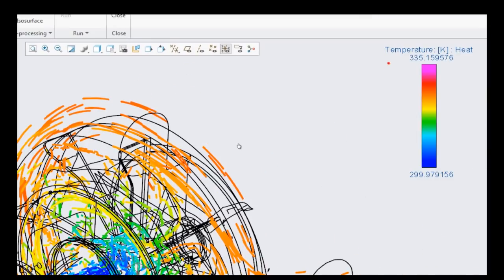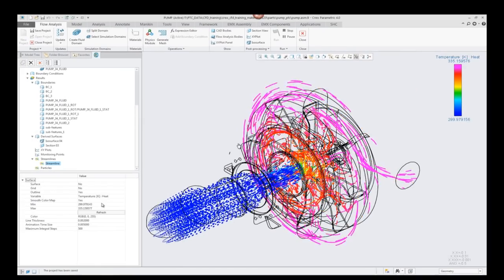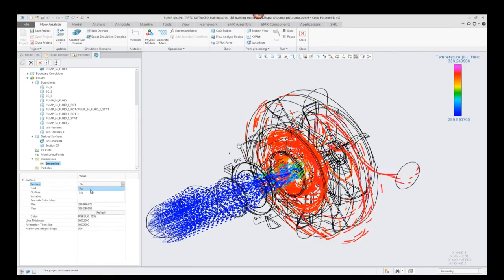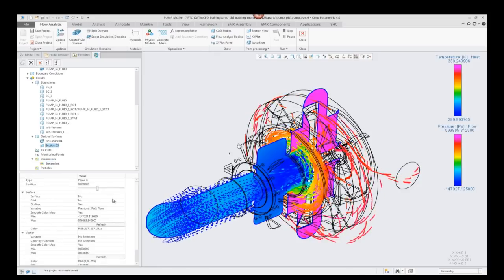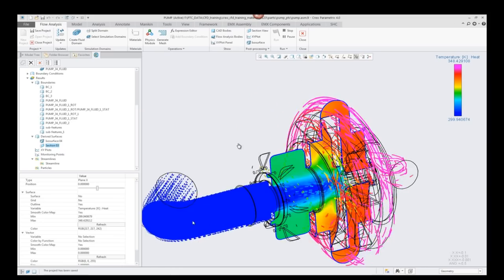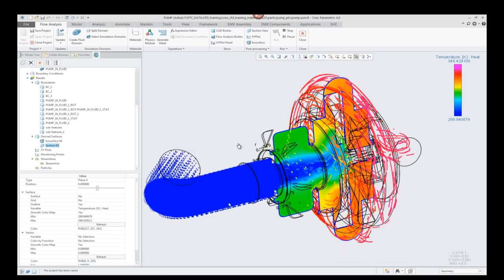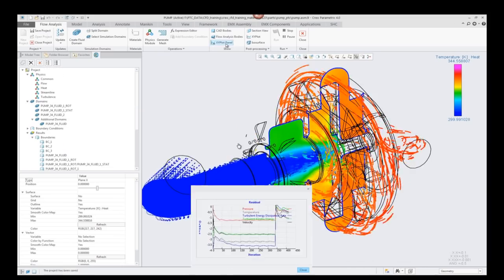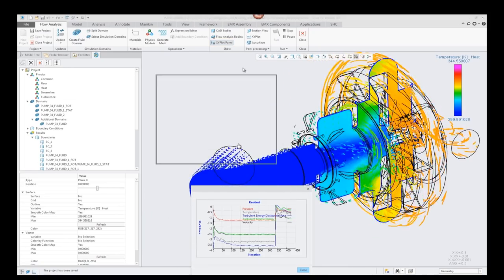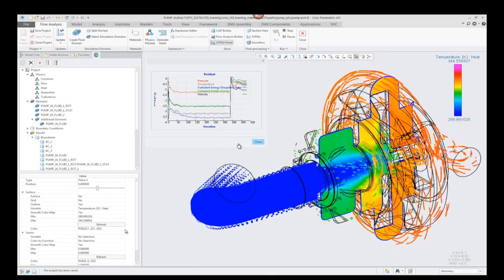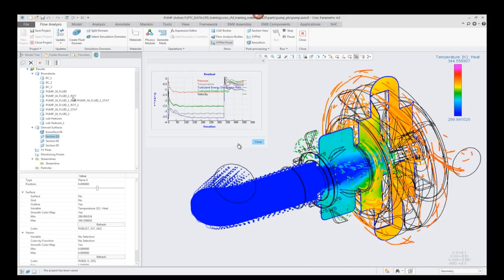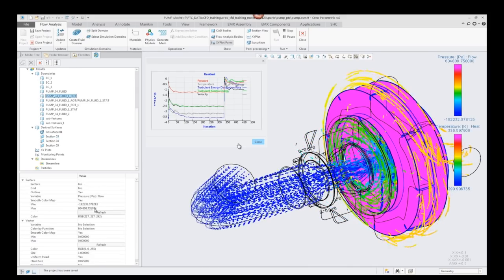And you can see that it's settling down now, and it's starting to refine the result, and we're getting something around a just under 40-degree variance, or it's gone up to about 50 now, variance between the inlet and the exhaust temperatures here. So this is quite interesting. What you can do is find out very early, if you increase the performance of your pump, what's going to be the impact on other components within that assembly.